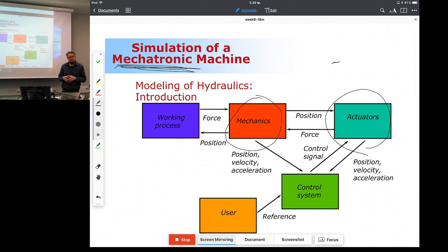Then you can maybe use a different type of oil to minimize the damage. Or the wild idea is to use water, just to replace the oil. This was quite much in fashion, say 10 years back. Not so much anymore, but water hydraulics is one possibility. Water hydraulics is typically quite expensive compared to conventional hydraulics. The expense comes from the fact that water is a lousy lubricant, and you have to use quite expensive materials in water hydraulics.